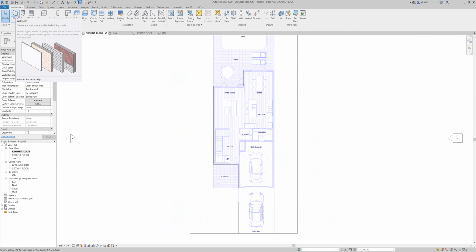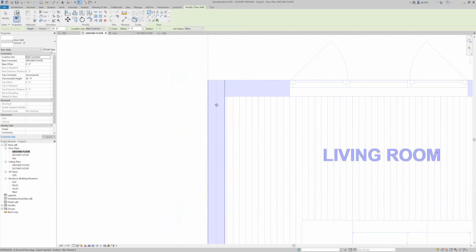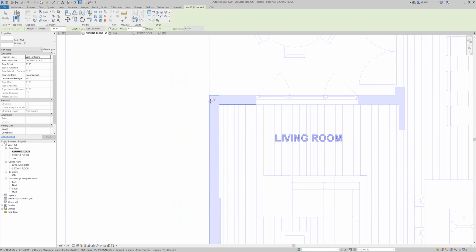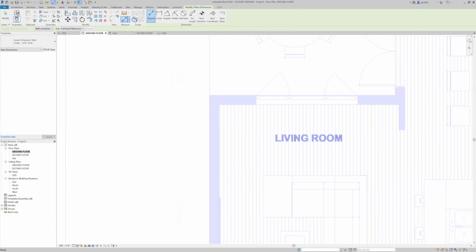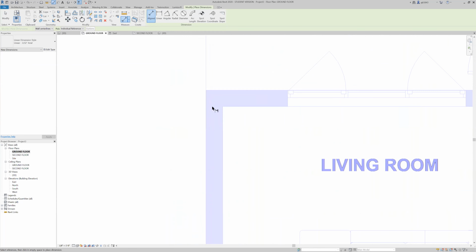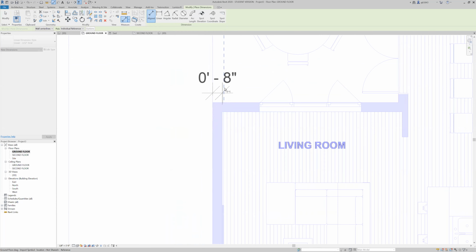Okay, so now we'll create walls. We'll go back to the architecture tab. And the first thing we'll do is, right now the basic 8-inch generic wall is selected. So we can start drawing them. I'm going to use one of these annotate tabs just to make sure that we're using the right wall type. So if I click on the outer face of the wall and then the inner face for this CAD plan, I can see that that's an 8-inch wall.